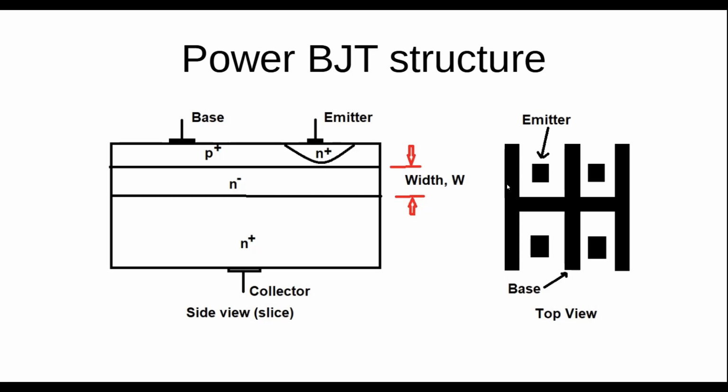So you can see that the base terminals are connected, and then I've not shown it, but the different emitters will also be connected. And at the bottom, you'd have a collector also connected. So instead of really thinking about this as a single BJT, within the package you have a bunch of them. And this is one of the reasons you can have a lot more current flowing through your system, as well as the fact that, of course, it's a vertical structure.